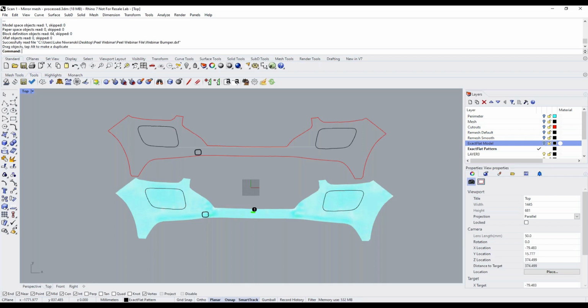Okay, so there's one other question I have along this line, and that is material properties themselves. So different types of film will have different stretch characteristics. And while ExactFlat does come with a database of common materials, if you wanted to have those stretch characteristics of your particular film applied to the flattening algorithms, just talk a little bit about that if you wouldn't mind, please. Sure. So we do have a material library, and we can choose different materials for use during the optimization process. We do use the mechanical properties of those materials.